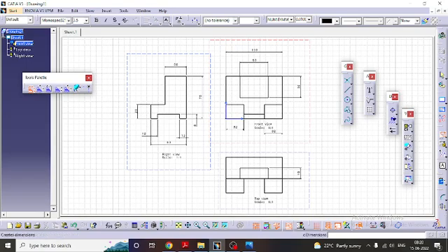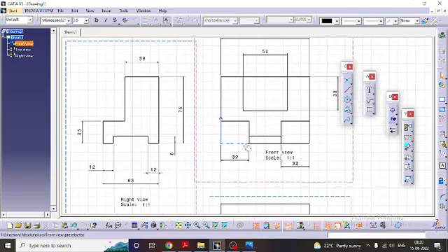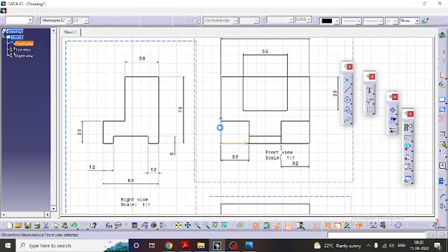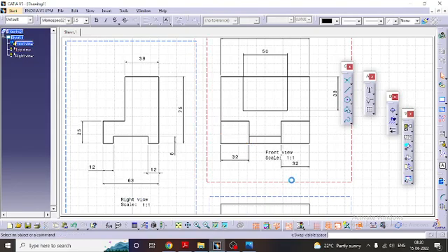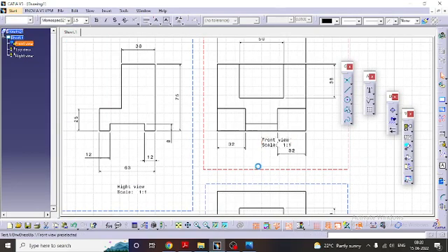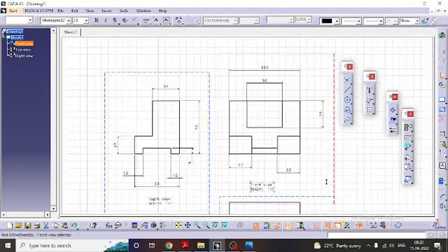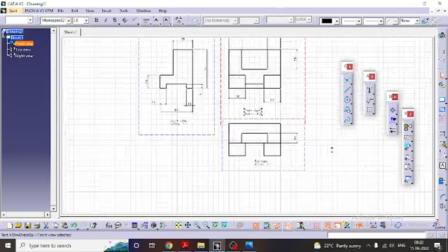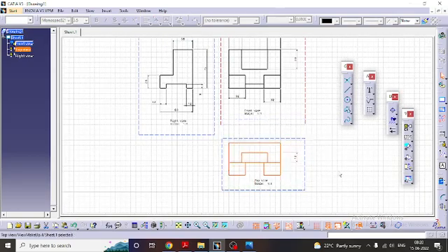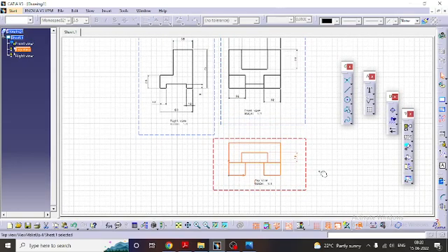So then this is the drawing. As I told you, you hide this one and this one, you have to hide this one also. Hide it, then just bring this front to just below it so that you can view the drawing clearly. Just pull this downside, then double click on this, then hide this one and this one also.